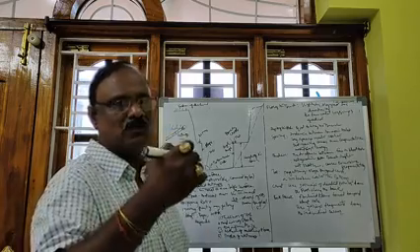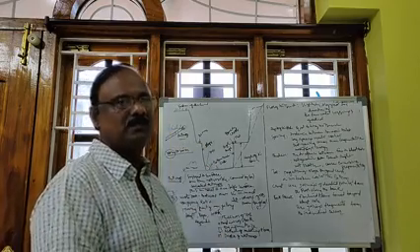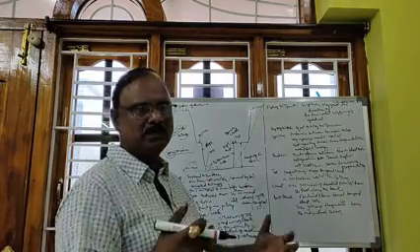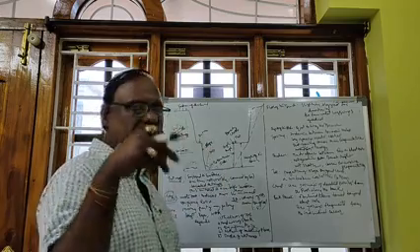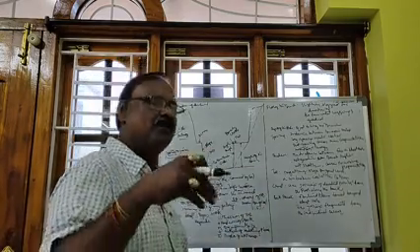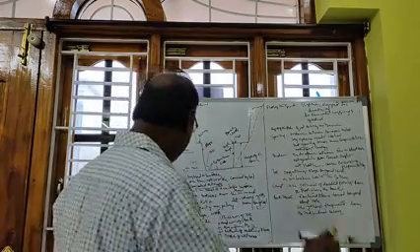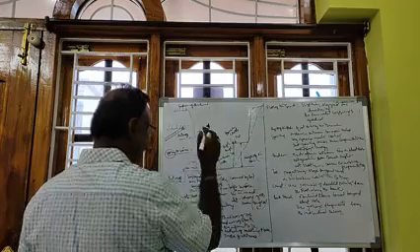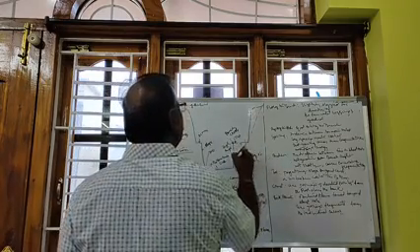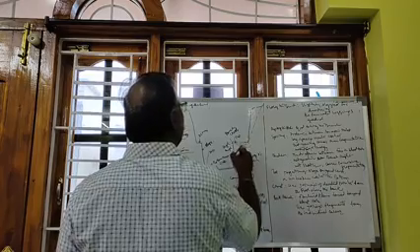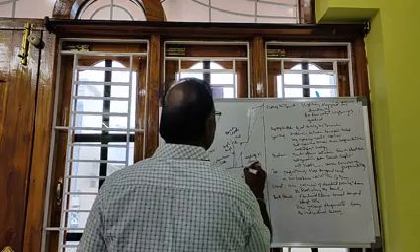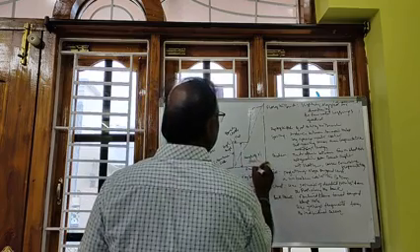For igneous rock, for strong rock, such as quartz rock, dolerite rock, and different other igneous rocks in the OB, the slope may be more than 45 degrees. There, mining is possible. So this is the slope of the bench and this is the height of the bench. The height of the bench is generally maybe 5 meters to 30 meters.